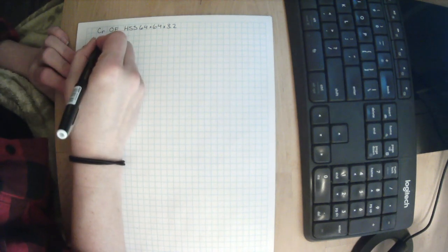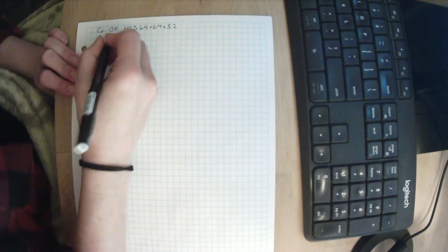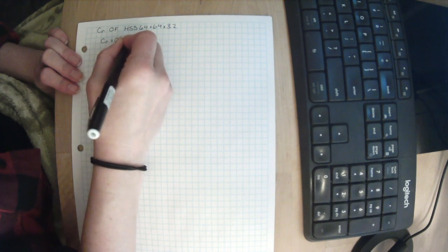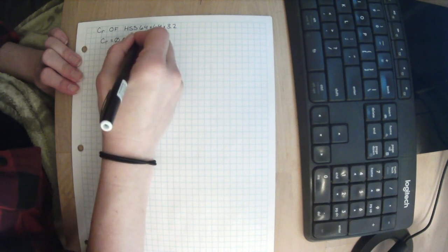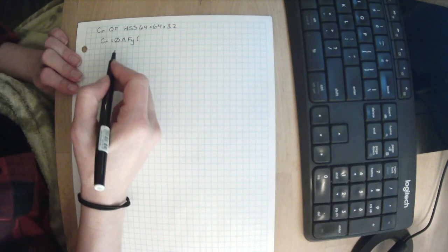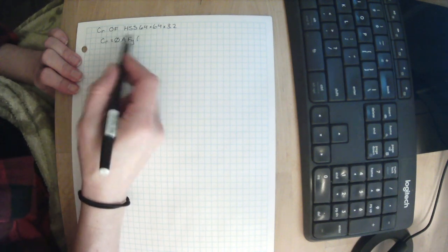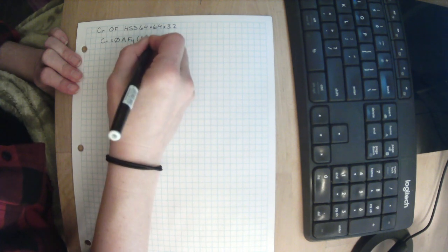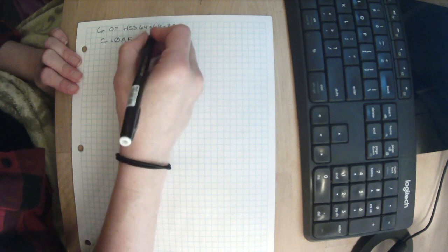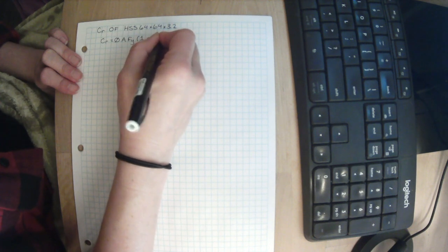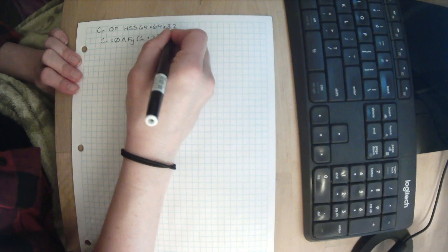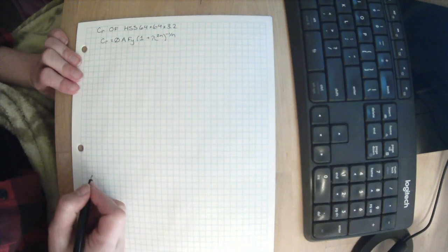All right, we know that the equation for CR is the reduction factor times the area times Fy, and that would be just about strength, but we have to worry about buckling as well. So buckling is 1 plus lambda to the power of 2n, and then everything in that brackets is to the power of minus 1 divided by n.